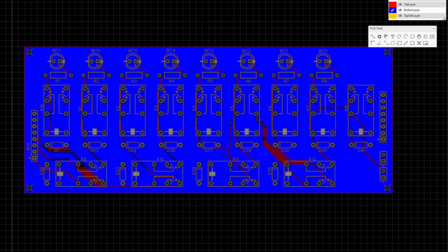There is a loop that goes from the normally closed to its own power, and then that goes to this relay here. So basically what happens is when power comes in, it causes this relay to click on, which puts normally closed on, which puts power through there around, and it basically keeps itself on. And it doesn't matter if you take power off, it's on. The only way to turn this relay off now is to cut the power coming into this pin.